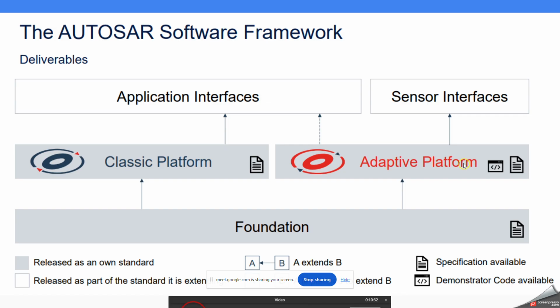We have some Qualcomm chips. So whatever SoCs are there, a system on chip, which support the Linux operating system, or your display panels, or whatever ADAS features are there, those features run on the adaptive platform. And the basic thing is that whatever microcontroller things, like engine control unit, communications, GPIO controls, sensor mechanisms, actuator mechanisms, all those things will be done on the classic platform. So mostly diagnostics will be on the classic platform.